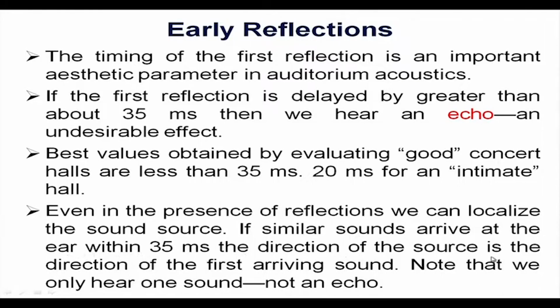Forget about the reading. What I said is, human beings perceive the direction of the sound based on the first arrival of the sound, which is the direct sound. So, we always perceive the sound's direction as the direction of the direct sound. So, if the reflected sound comes within 35 milliseconds, it does not create another sensation of the same sound. So, we do not hear an echo. So, the direction of the sound will be the direction of the direct sound.